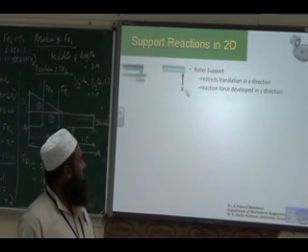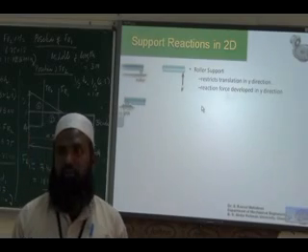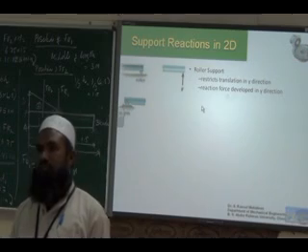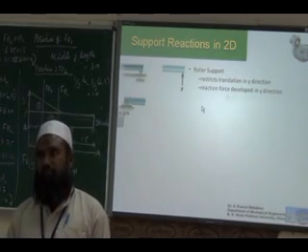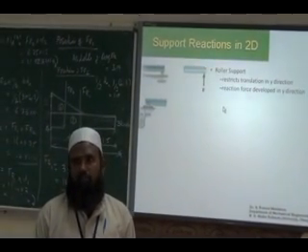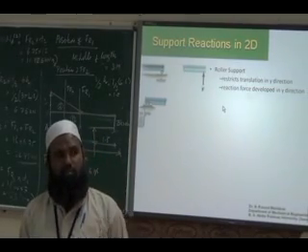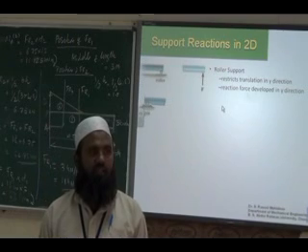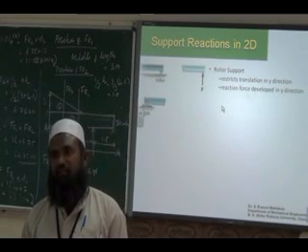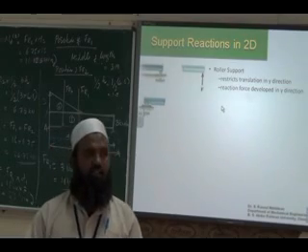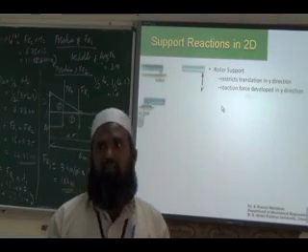So there is a reactive force. This joint, can you see, is a pin joint. Okay. So what type of restriction do we get? It's a hinged joint, a hinge. So it can rotate. Translation is restricted. It cannot translate in the y direction as well as the x direction.